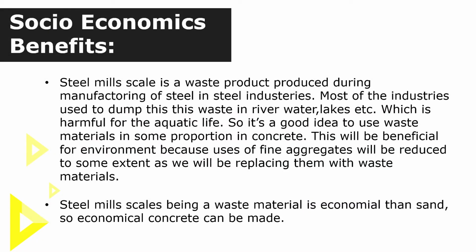Some of the socio-economic benefits of our project are: as steel mill scale is a non-recyclable hazardous waste product and it is dumped into water or landfill, which causes pollution, its use in concrete to some extent will have a good effect on our environment. It is a waste product, so it is more economical than sand or other fine aggregates. So by using this, we will also be making a less costly concrete.